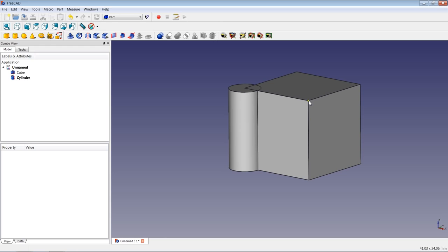With the Inventor navigation mode, you have to press Control and then click on the element you want to select. Please note that the 3D navigation styles are hard-coded, which means you cannot customize them. You just can choose between the three styles and you stay with one style until you want to change to another style.